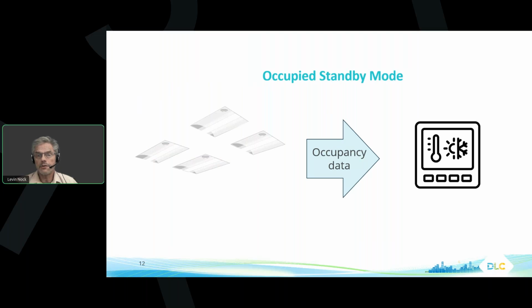If you have an existing building with variable occupancy patterns and you want to add occupancy control to save HVAC energy, then a lighting retrofit project offers a great opportunity to install light fixtures with occupancy sensors already built in and networked wirelessly and powered by the same circuit that powers the lights. All those sensors get conveniently installed in the ceiling of practically every space in your building that's ever occupied.